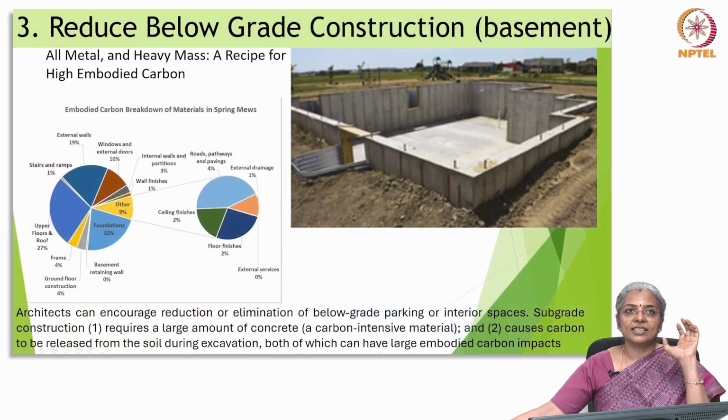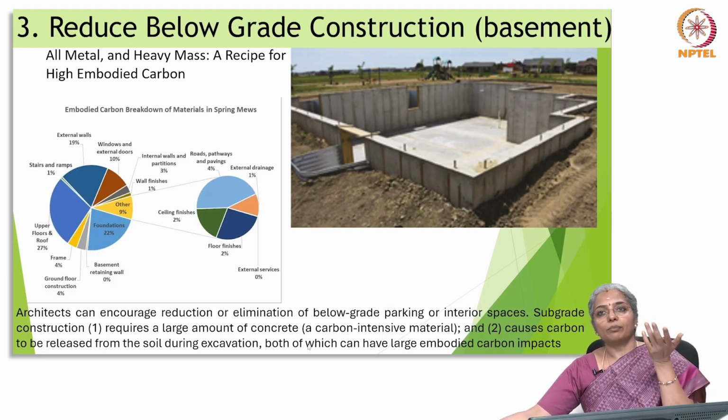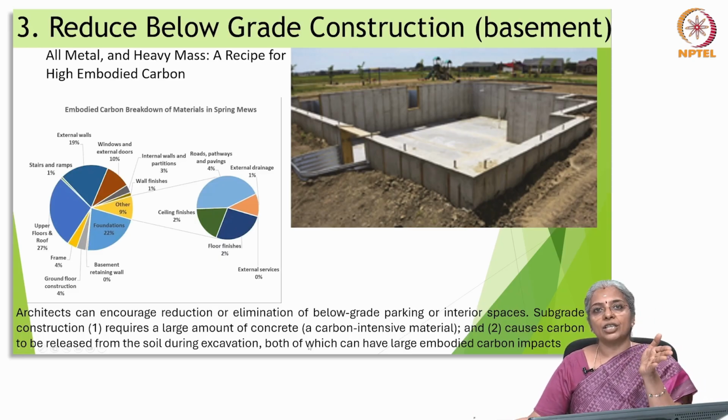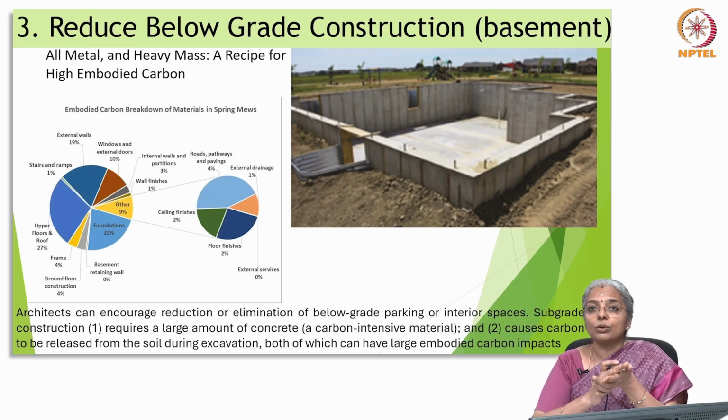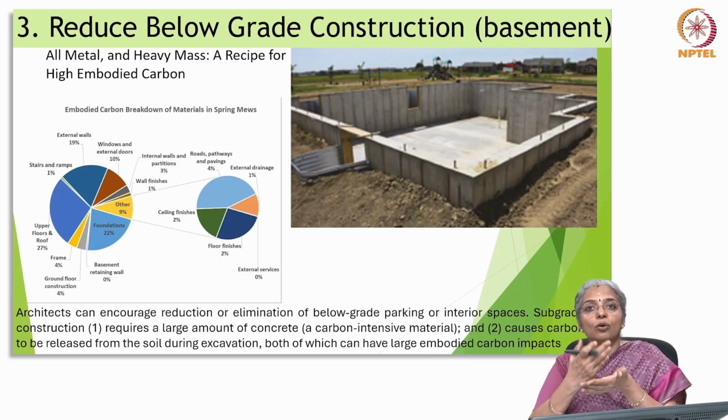The third strategy is, you need to reduce below grade construction, which is actually basement, because architects can encourage reduction or even elimination of basement parking, and because of that a large amount of concrete can be saved, because concrete is a carbon intensive material. Also, carbon that is released from the soil during excavation can also be saved. So, both of these can lead to large embodied carbon impacts.